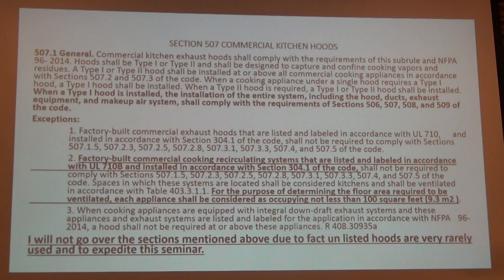Most are. But then again, how about that section, Mark, where it says you can't bring in air more than a 10-degree difference than the room temperature? Well, it's saying in that code that you have to provide air conditioning, because it has to handle the latent and sensible heat gains caused by the appliance.